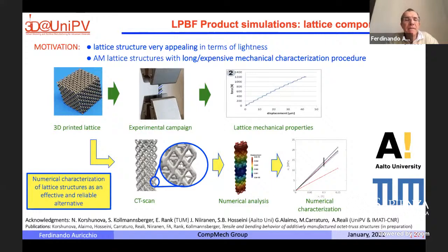With additive manufacturing, when you want to make a light component, so you want to distribute material with low density, you end up making very tiny structures inside the material, and you try to make these structures very, very small. What's the issue? When you make the structures very small, very easily you end up with a geometry which is in the range of the technology precision.